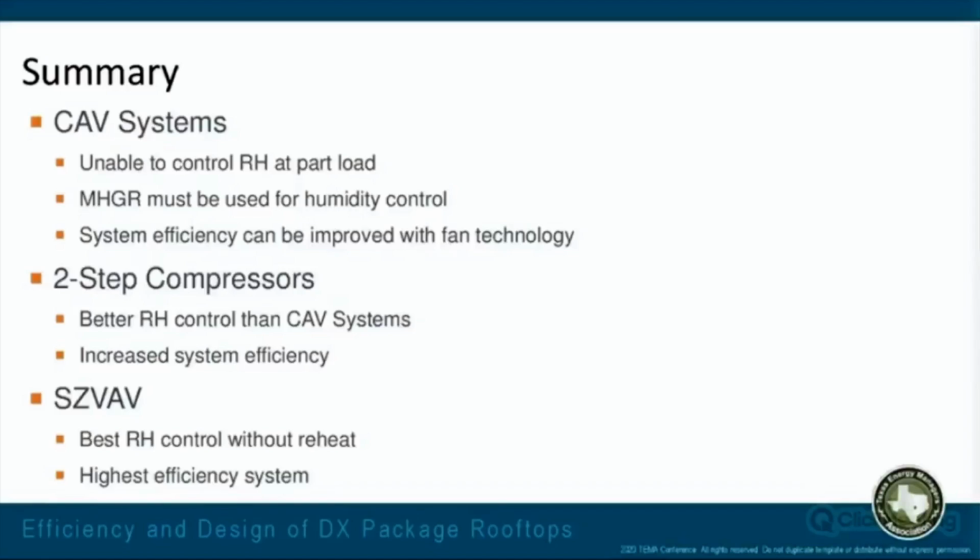And then your single zone VAV system will have the best relative humidity control without going to modulating hot gas reheat, and have the highest overall system efficiency, meaning the lowest energy use for the same condition in that space throughout.